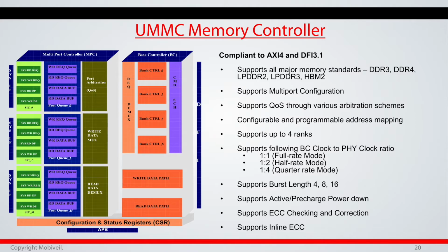And this is the memory controller. It's a universal multi-port memory controller that we have. It's DFI, because all these controllers we have are digital. So this is the DFI on one side, and AXI towards the system interface. And it is multi-port. We can have multiple slave interfaces based on how many masters you really want to attach this controller to. And we can support multiple ranks.